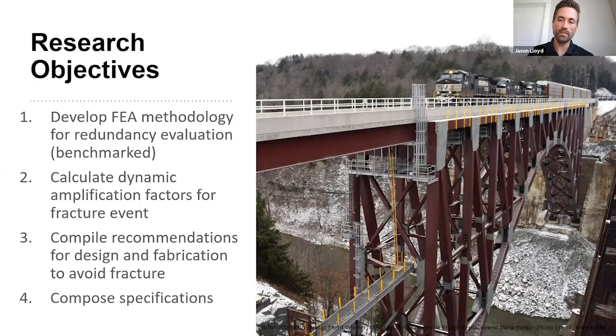Thirdly, steel bridge fabrication and design procedures were reviewed to develop a set of recommendations to avoid occurrence of fracture. And then finally, a comprehensive set of specifications were written with the intent of providing bridge engineers with the methodology for the identification of FCMs and SRMs through redundancy evaluations and a set of requirements to prevent fracture in steel bridge members. The proposed specifications were submitted to AASHTO's T14 Committee on Structural Steel Design for balloting and adoption.